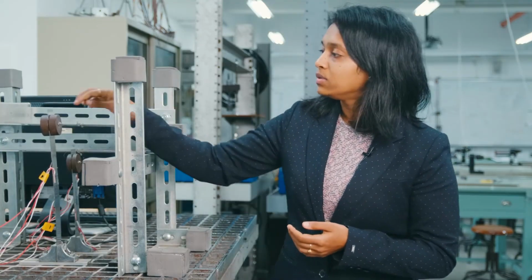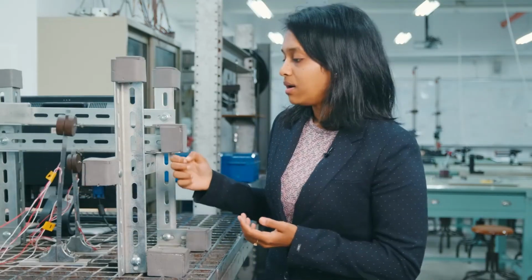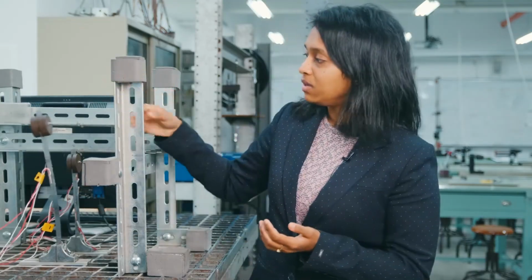We are going to subject this to free vibrations like this, and there are strain gauges on the plate through which we are recording the response under free vibrations, and the software program is able to calculate the measured frequency. You are expected to compare the measured frequency for the 4 different scenarios with the calculated natural frequency.